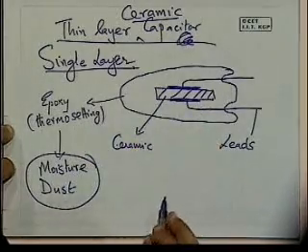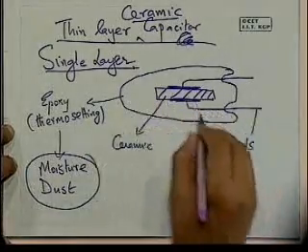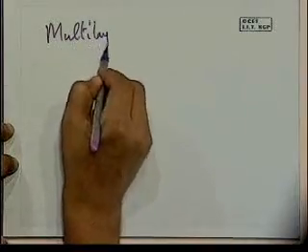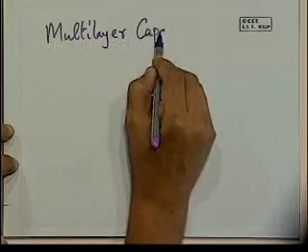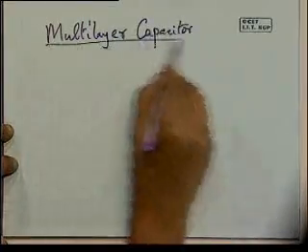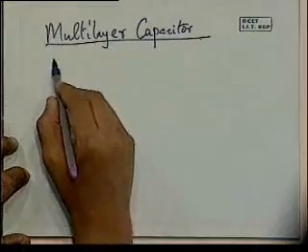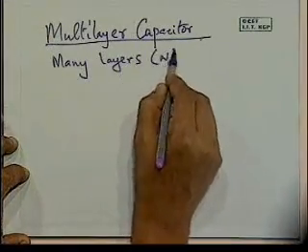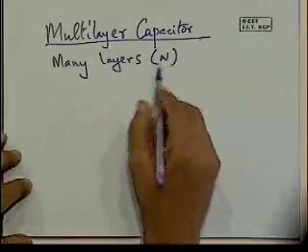the particular ceramic. Now, this is what is called the single layer capacitor. I can increase the total capacitance by connecting a bunch of these in series. And yet I want to do that to be as compact as possible. So the idea is, in a multi-layer capacitor, we are essentially doing the same thing as what we had for the single layer, except we have stacked it up. There are many layers, say n layers of the dielectric, and they're connected by electrodes. They're just stacked up.